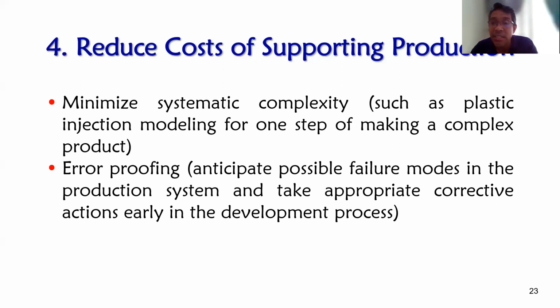So the single diameter of plastic, for example, we have to make one part, one rod, for example, using the extruding machine. So with a single extrusion, we can get a single diameter plastic rod. For example, with the plastic pellet, we put the plastic pellet in and then we extrude it, and then we get the plastic rod.